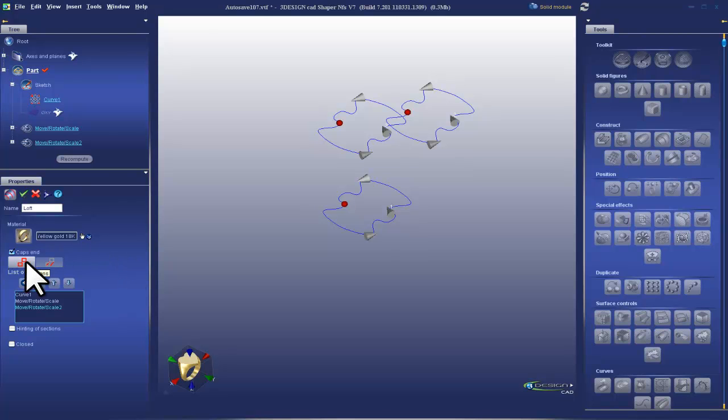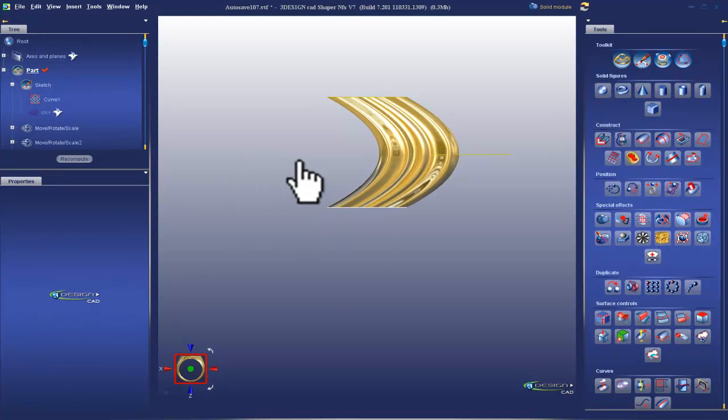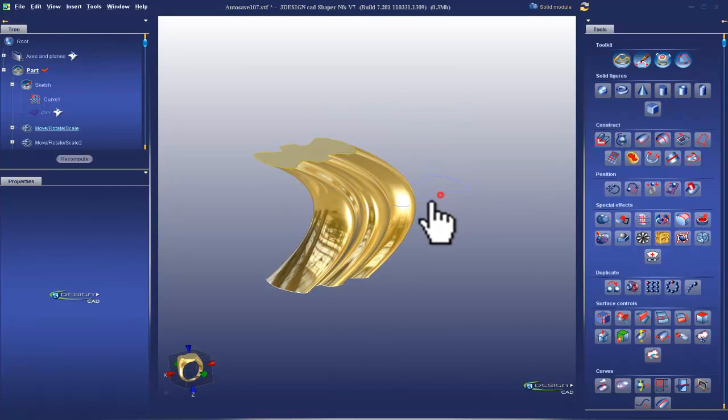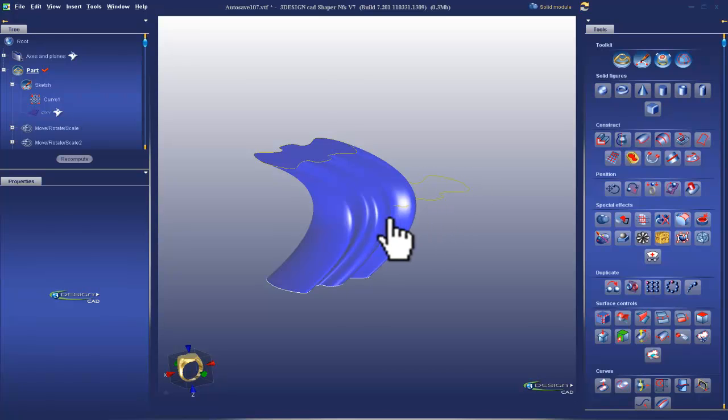This is the Sections tab. The next tab is Paths. So under Paths, I have Interpolation mode. I'm going to validate on loose, and you can observe what happens. So notice that this cross-section is not, the loft is not fully realizing or not fully meeting the confines of this cross-section.